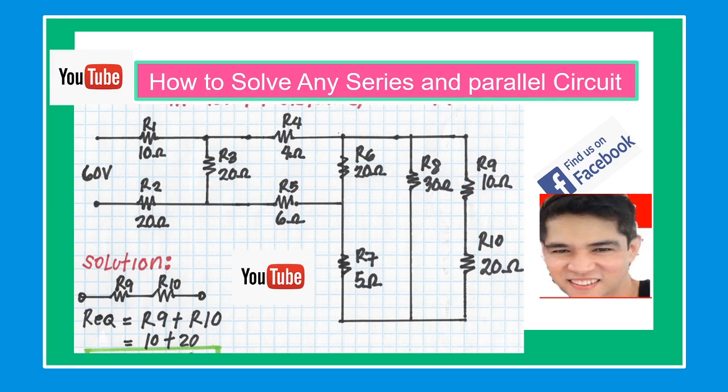In a series circuit, the current that flows through each of the components is the same, and the voltage across the circuit is the sum of the individual voltage drops across each component. In a parallel circuit, the voltage across each component is the same, and the total current is the sum of the currents flowing through each component.